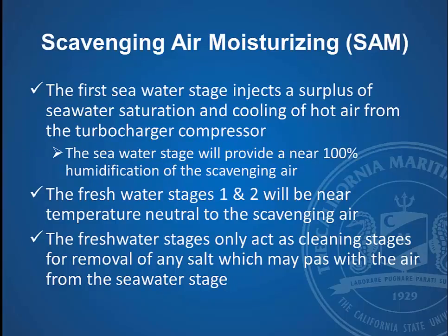So, scavenging air moisturizing. This is Burmeister & Wain, their latest one that's in development. And you have a first stage. Seawater injects a surplus of seawater for saturation and cooling of hot air from the turbocharger compressor. The saltwater stage will provide a near 100% humidification of the scavenging air. So you're atomizing and blowing salt water into the intake of this engine, and that's going to cool that hot scavenging air and its heat of compression from your turbochargers. It's going to cool that down, and it's going to humidify it.